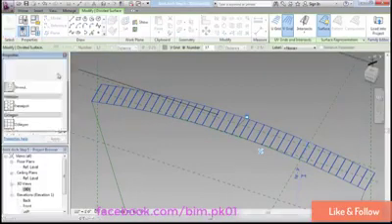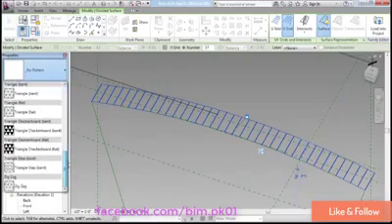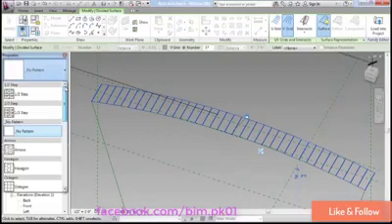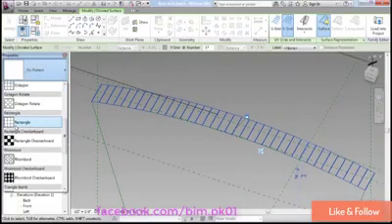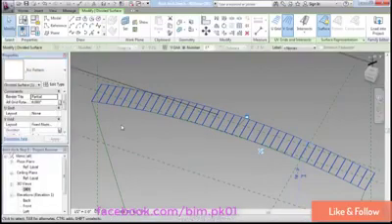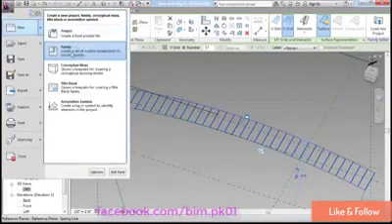If you open up this list here, in the massing environment, they have all of these built-in patterns. What we need to do is actually go in, we're going to use the rectangular pattern. We need to go into the rectangular pattern and create a panel family. And that's going to be of a single brick. And then that panel is going to get loaded in here and give us our individual bricks. So I'm going to go to the big R. I'm going to go to New and choose Family.